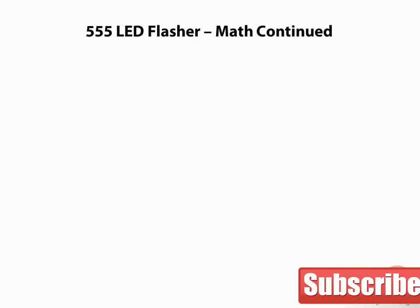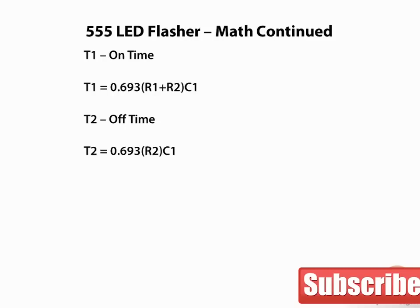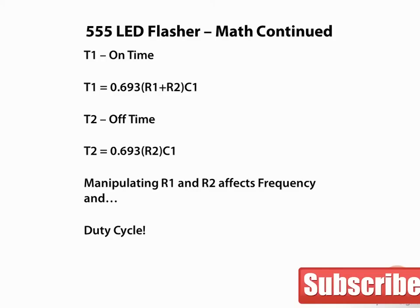For those who are interested, T1, or the on time, is given by the equation T1 is equal to 0.693 times R1 plus R2 times C1. And the off time, T2, is given by the equation T2 is equal to 0.693 times R2 times C1 for astable operation. We can see by manipulating the values of R1 and R2, we can adjust not only the frequency of the oscillator, but also the duty cycle. Try it out and see if you can think of some neat applications for this versatile circuit.